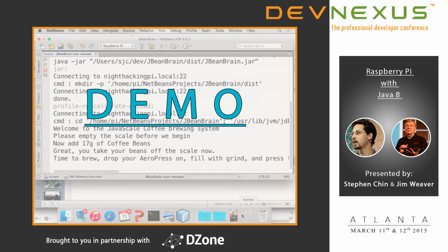And there's a bunch of them, and they vary in different features and performance. Like this one has a heated bed, which is really nice. So I don't need to use glue. And when the print cools, it just pops off the plate. A common problem with 3D printers is getting your prints to not stick on the plate. So heated beds are really nice for that.